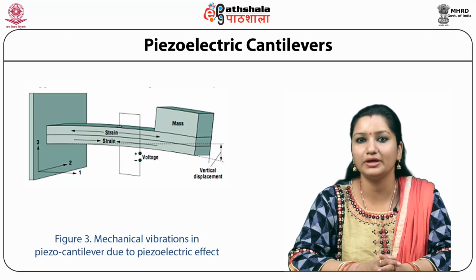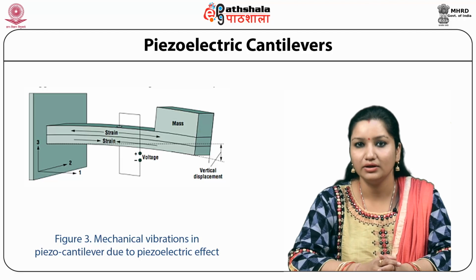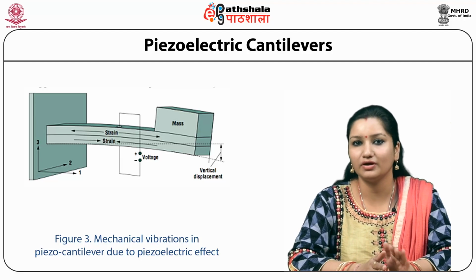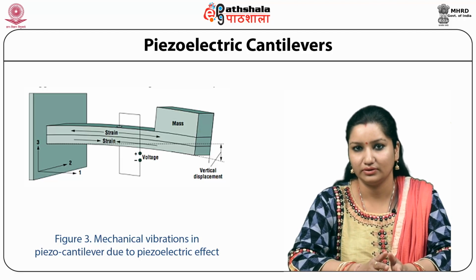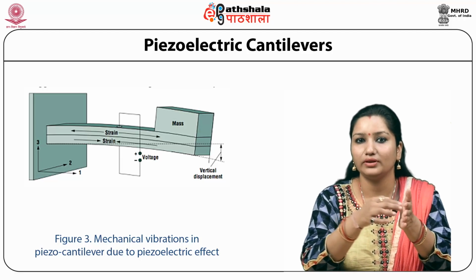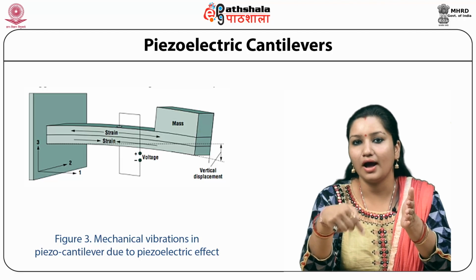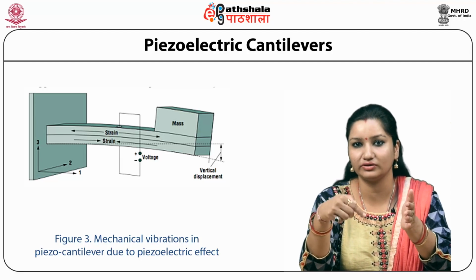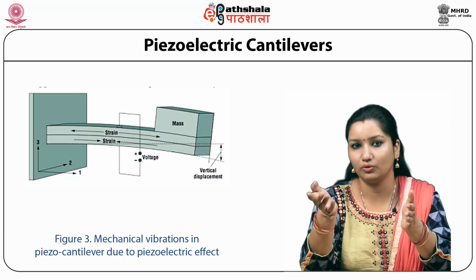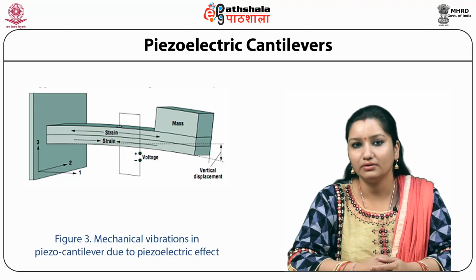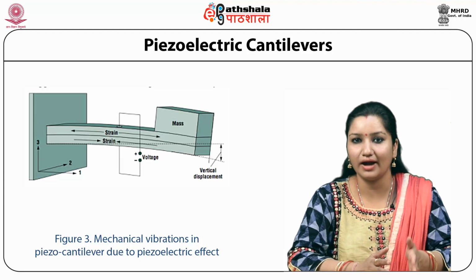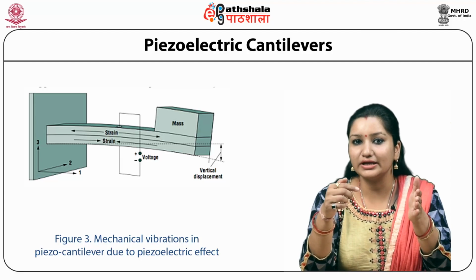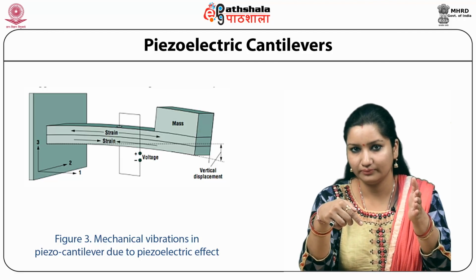The vibration of the beam is induced by its own inertia. Since the beam is not perfectly rigid, it tends to deflect when the base support is moving up and down. You can see this phenomenon of deflection in the figure given below. Typically, a proof mass is added to the free end of the beam to increase the deflection amount.